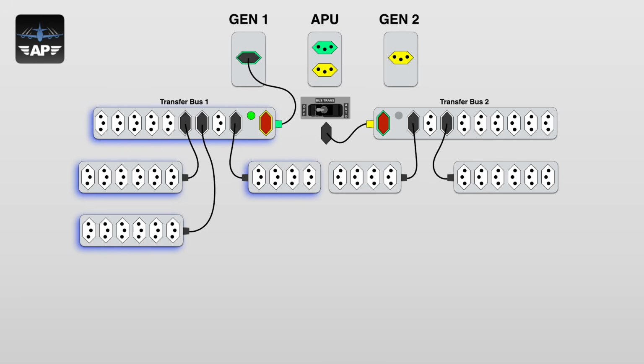There is no parallelism between AC power sources. And what does that statement mean? It means you cannot connect your bus to two power sources at once. It's like trying to pick one plug and connect to two power outlets on your wall at once. It is impossible. You have to pick one. Either an engine generator, an APU generator, or stealing from the opposite bus. But never two options at the same time.